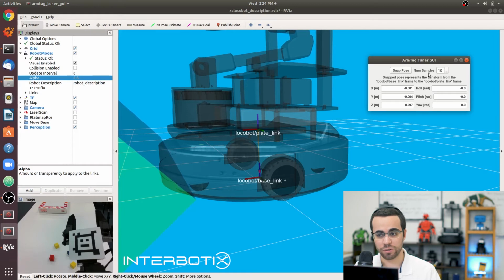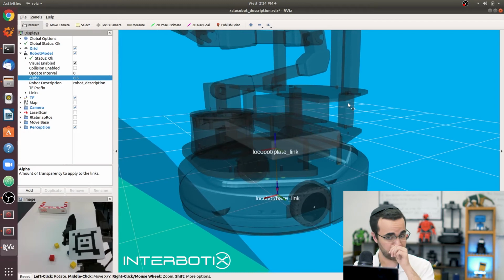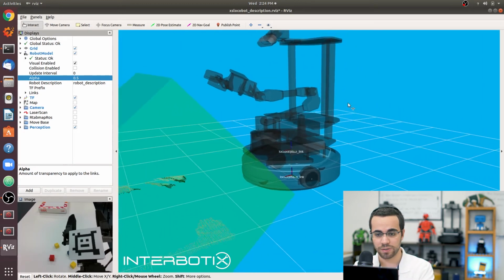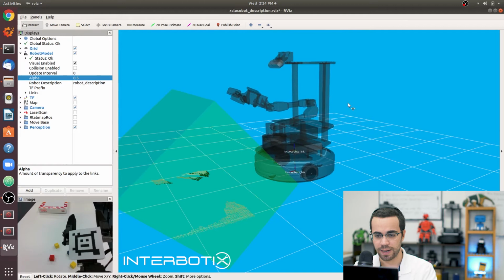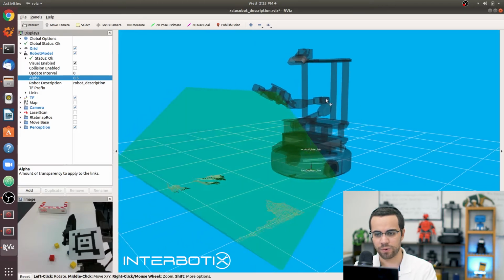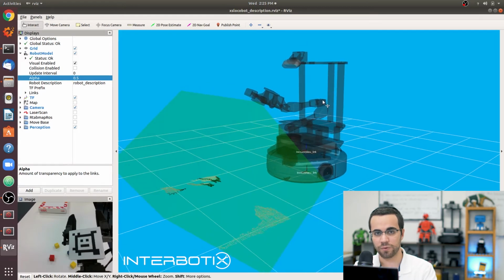And if you don't want to load this calibrated pose to the TF tree when you want to work with the physical robot, you could just leave use_static_transform_pub to be false, and it'll just use the transform defined in the URDF. Okay. As far as actually tuning the filter parameters, I'm going to explain that right after this. And it works the same way for both the LoCoBot and the standalone arm.